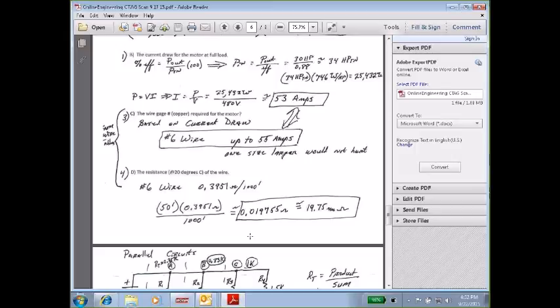But think about it. That wire, number 6 wire, is pretty good size. And we're only talking of 100 foot of it. So, you know, we're talking about a pretty good sized pipe, if you will. And how much resistance is there to water to flow through a big pipe if it's only 50 feet long? Very little. Well, the same thing electrically, if we're talking about the resistance of this electrical wire, and it is a large diameter wire, and it's only 50 feet in length, then the resistance would be very, very small.